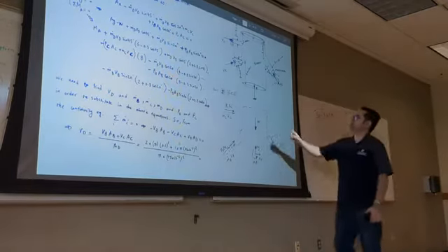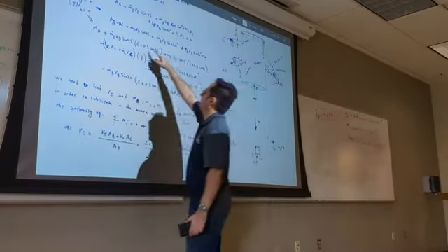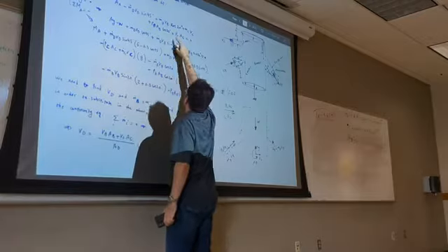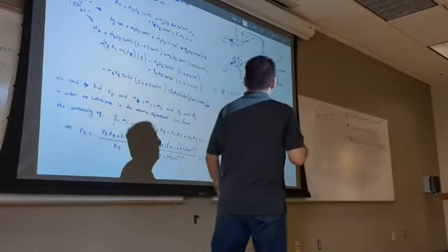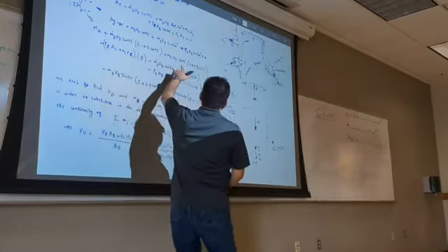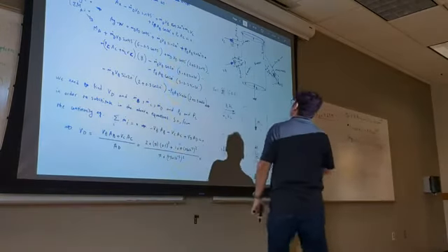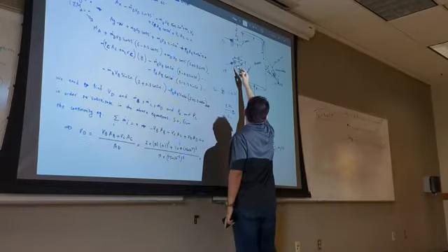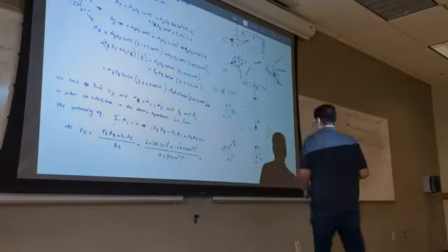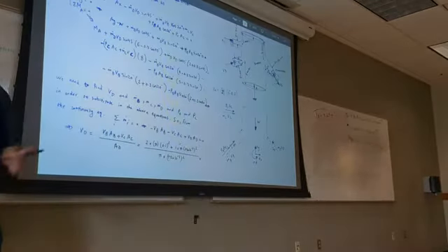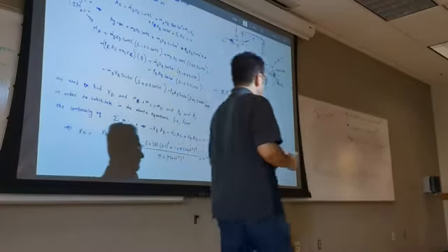Now, we have m dot D. And the only thing I need to find in order to be able to solve for AX, AY is to find PB, you see that? And PC. In fact, if you get that, you can also solve for the moment according to this. Now, how can I get PB, the pressure here? So for that, we reached this discussion, the Bernoulli and the assumption.